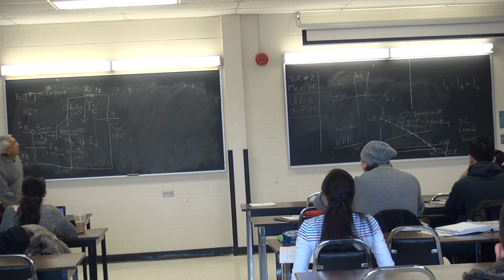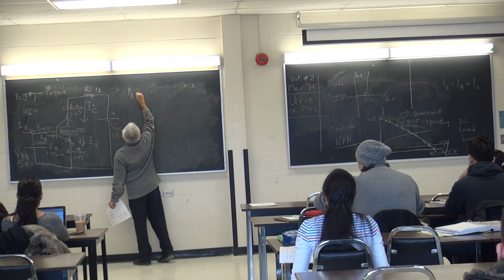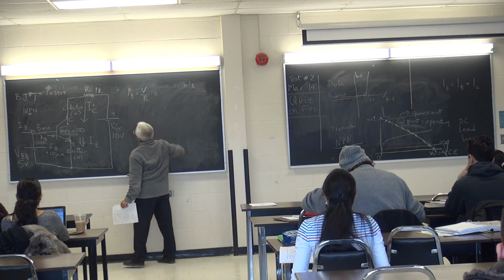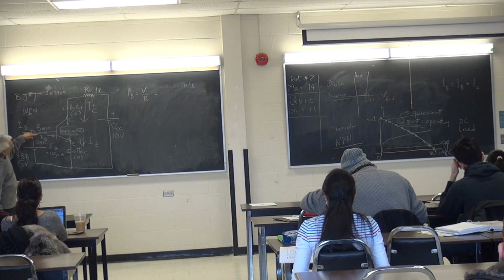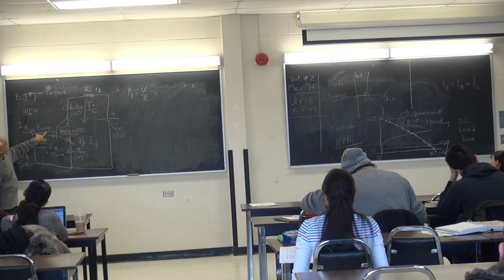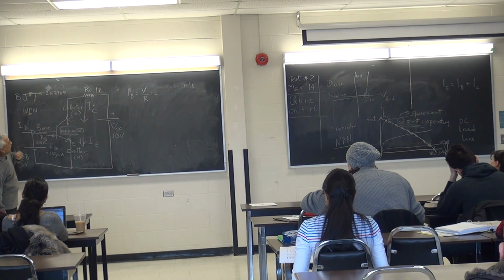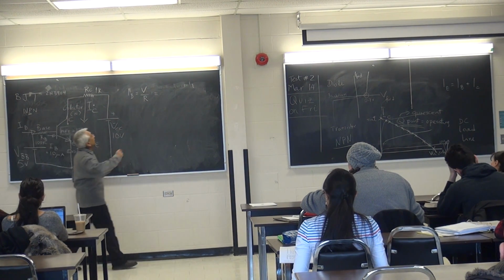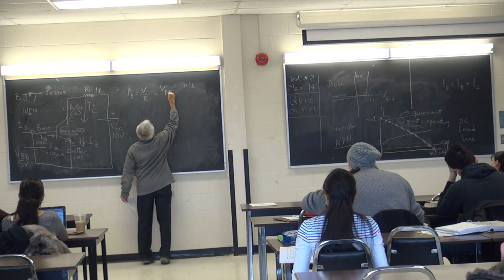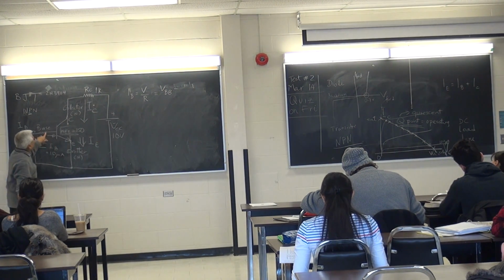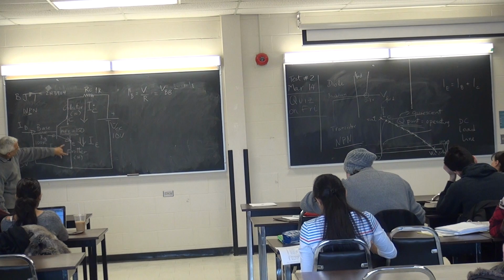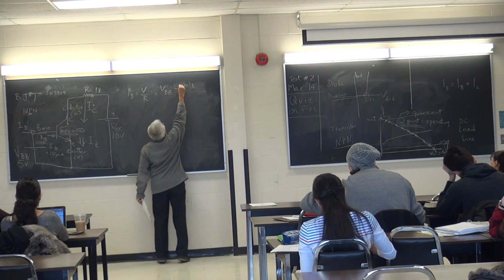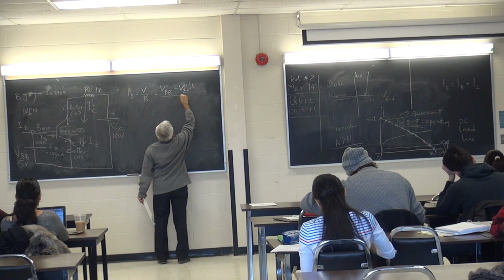And this current IB is V over R, Ohm's law, which happens to be, imagine the current to be the current in this resistor here, which is IB. So, the voltage on the left minus the voltage on the right divided by R. So the voltage on the left is VBB. The voltage on the right is this voltage here, from the base to the emitter. Okay? So that's VBE divided by RB.